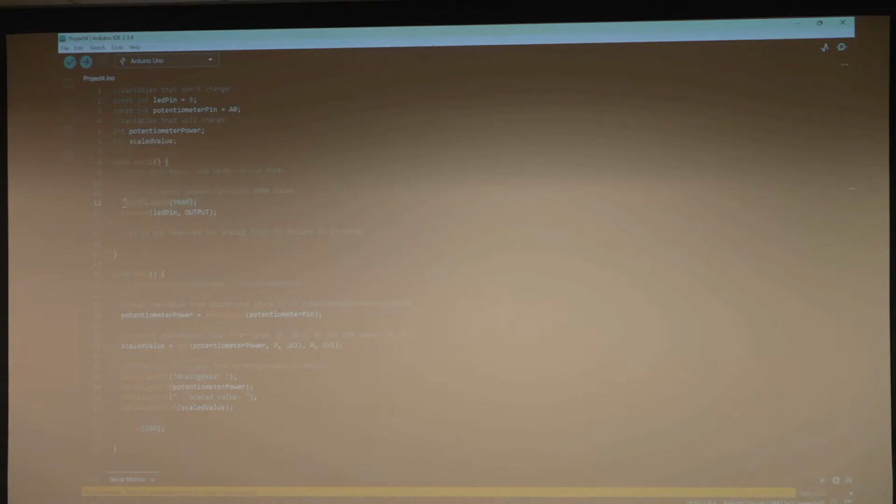So to use it, it's not the terminal in Arduino environments because we're using an electronics board. But we are using a serial communication protocol, so you just say it by typing serial.begin, and the argument is the baud rate, which is, let's say, a frequency that Arduino will listen to the port. And then the most important one, I would say, is where the logic comes, which is in the void loop.